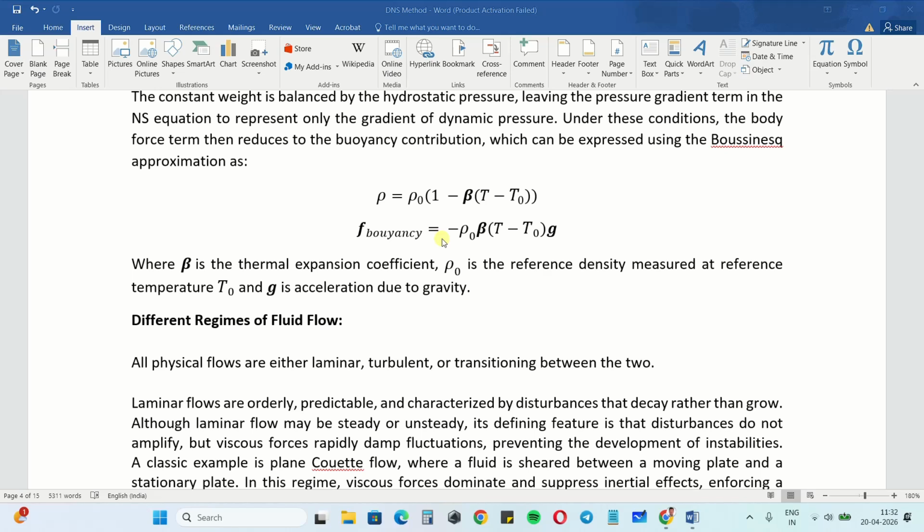What we will be solving for is the dynamic pressure part, and in the body force term what we will have is this buoyancy force term. Okay, so to define the solver, we will be specifying this beta coefficient of thermal expansion, and we will have the gravity file in the boundary conditions, and so on. So that's the final thing that we want to check. So we will be solving a modified Navier-Stokes equation with this Boussinesq approximation.